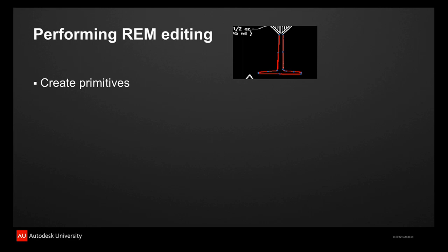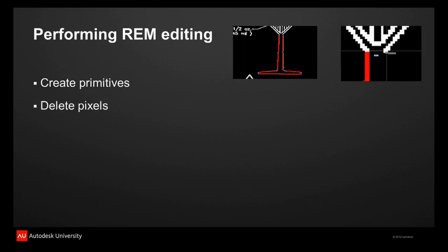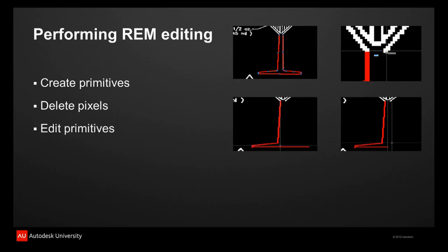So if I convert this to vector data, it's not going to be of much use. It will be inaccurate data. So I want to take this image and improve on the existing raster information before I start vectorizing it. This is what I'm going to do. I start tracing those objects by creating primitives. It's very simple. You click on the Create Primitives drop-down. I used the Smart Pick here, and it actually worked quite well. So I just used Smart Pick and started tracing these elements.